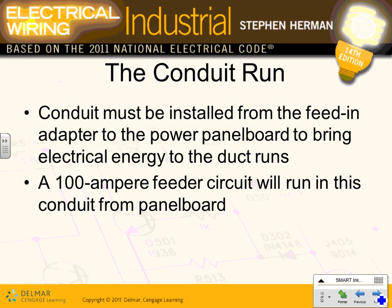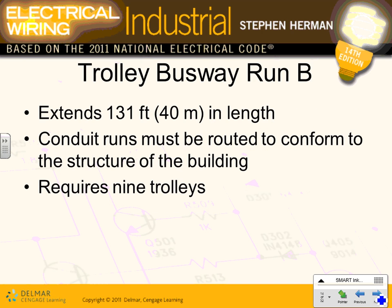And then the rest of it, guys, is you have to have a conduit, like we said, all the way from the feed-in adapter all the way to the panel. So you need to feed the trolley busways. Here's my trolley busway right here. I need to bring a conduit from here all the way to the panel to feed it. A 100 amp busway feeder circuit will run in this conduit, so you have to have a 100 amp circuit breaker with conductors inside the conduit. That's just how you feed the busways.